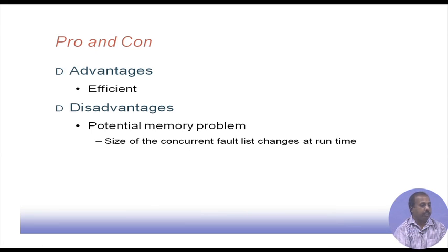Advantage, this is efficient definitely, but the disadvantage is the memory problem, because in concurrent fault simulation I need to remember a number of bad gates for every good gate. So, I have to remember more gates, which means more memory and runtime complexity.